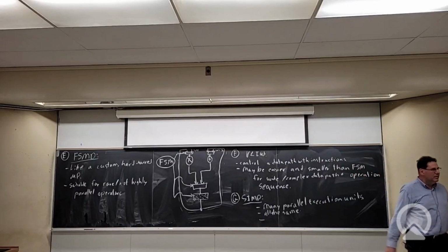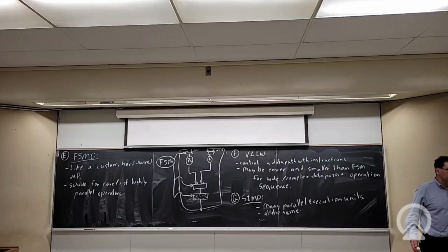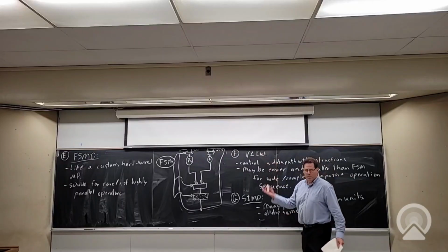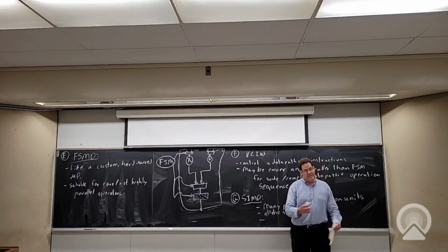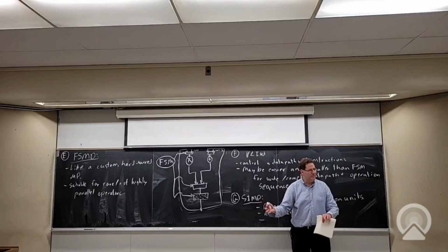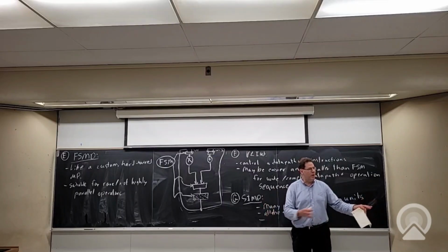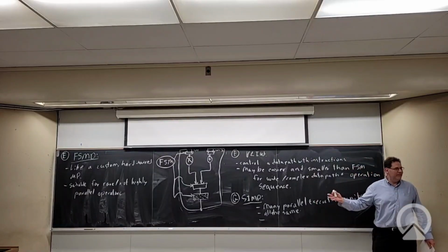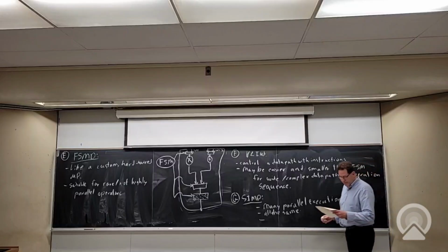Yeah? Because for highly parallel flows, it reduces the amount of memory you need because you need to store small instructions. Yeah, so if my VLIW was just 50 multipliers and they tend to operate kind of in lockstep, like you multiply this number, I'll multiply the one right next to it, I'll multiply the one right next to it. It's kind of wasteful to encode that all individually. Okay, so you could do that, but it's wasteful.